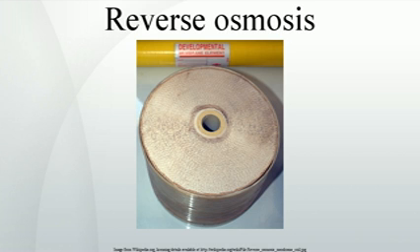Positive displacement axial piston motors have also been used in place of turbines on smaller systems. Turbocharger, a water turbine driven by the concentrate flow, directly connected to a centrifugal pump which boosts the high-pressure pump output pressure, reducing the pressure needed from the high-pressure pump and thereby its energy input. Similar in construction principle to car engine turbochargers.